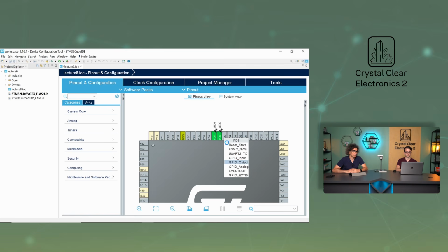While Donny is writing this, I will tell you how fast the I2C protocol can communicate. At the time of the video being shot, the I2C standard supports 5 speed classes. These are called the standard mode, with a speed of 100 kilobits per second, the fast mode with 400 kilobits per second, the fast mode plus, which can reach 1 megabit per second, the high speed, which can transfer data at 3.4 megabits per second, and the latest ultra fast mode, which can reach 5 megabits per second.